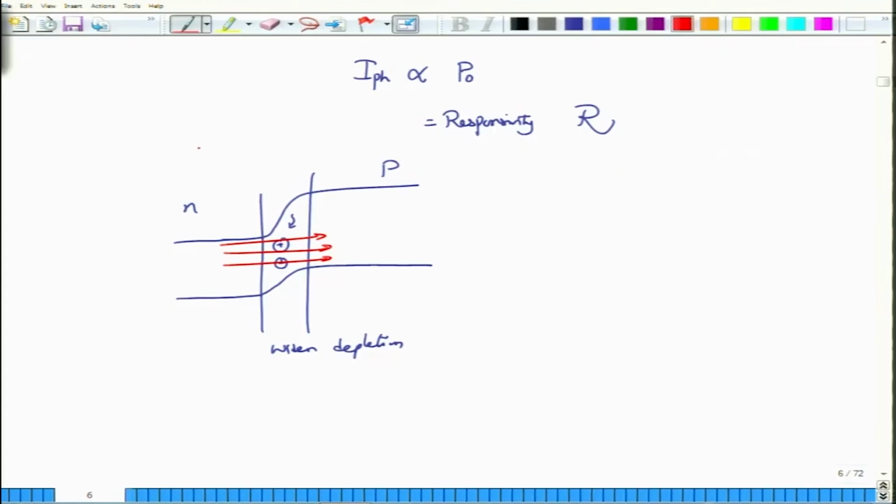So, the photodiodes are to be reverse biased, so that no current or very little current flows, which is called the dark current, when no illumination has taken place on the photodetector. This dark current is also sometimes called the reverse saturation current of a PN junction. So, only this current flows when the photodetector is not illuminated. But once the photodiode is illuminated, and you realize that there is already an electric field that points from the N type material to the P type material, any electron hole pair that is generated in the depletion layer will very quickly attain a large velocity.